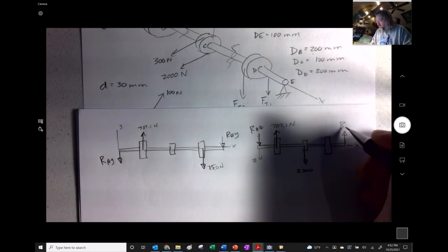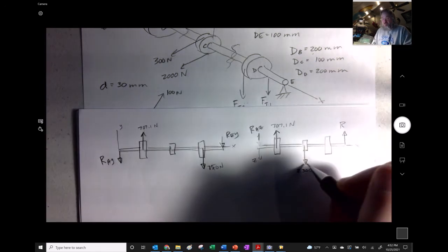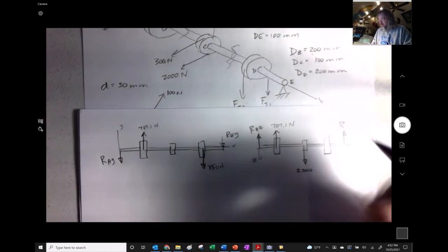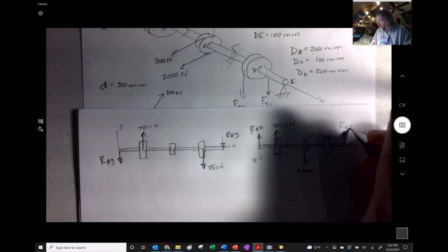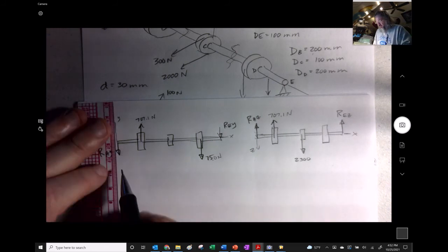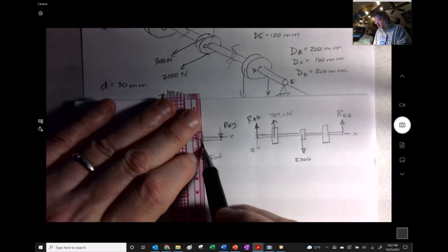You know, I really think that they both should be coming up. So I'm going to guess they're both up, because this one's in the middle, right? And although this one's close to that right there, I think this one is going to go that direction. So this is our res right here. And just making our shear moment diagram underneath this.